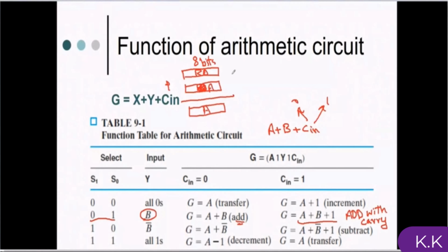And we have an instruction with a special register known as the accumulator and a register, for example, R0. So this instruction in 8051 assembly language means that I'm going to add the accumulator with R0, and the answer will be inside the accumulator as the result.